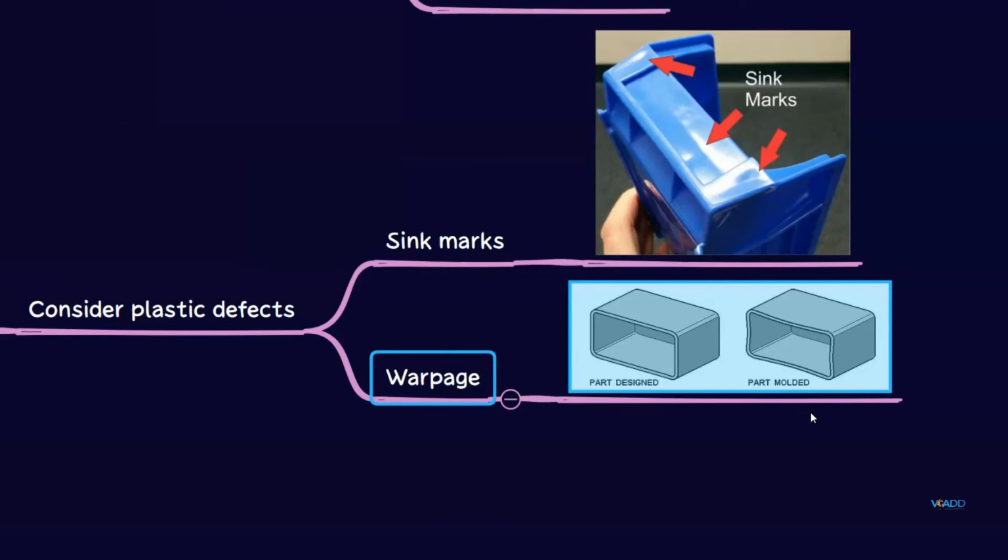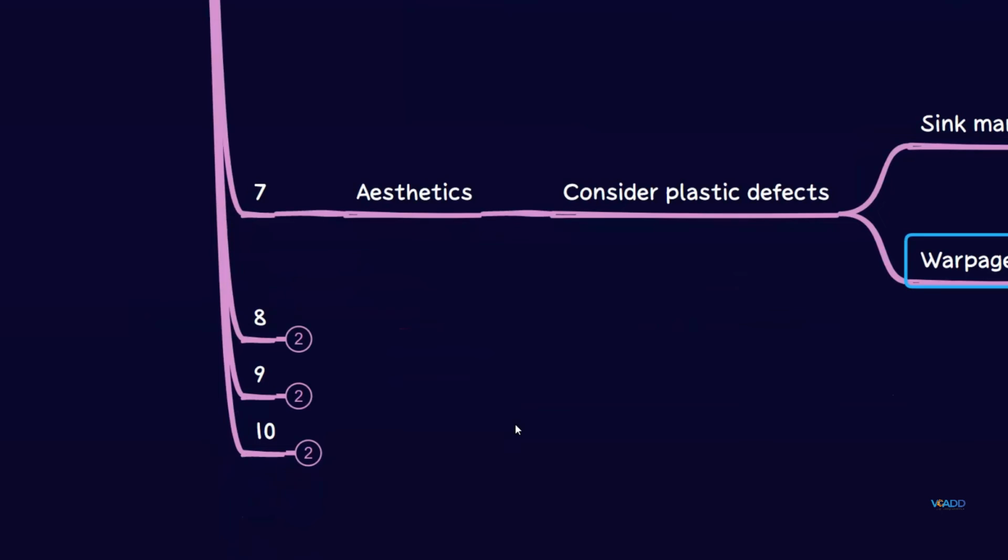Otherwise, your part will be warped. So your design will be like this, but your molded part will be like this, which will be rejected by the customer. So this is the important factor. You should consider the aesthetics also. It should not affect the aesthetics.